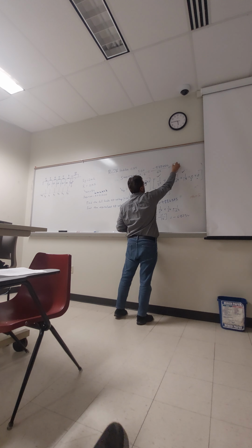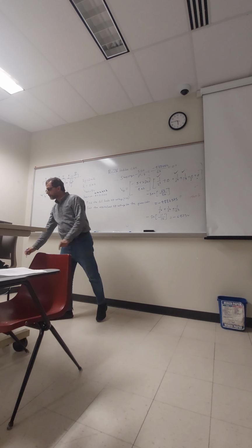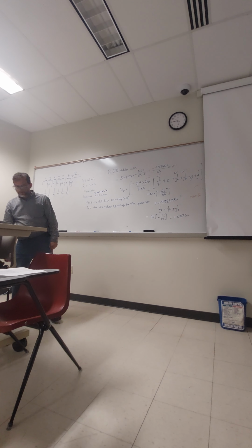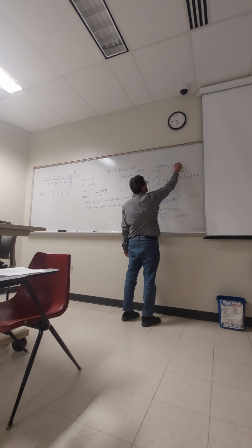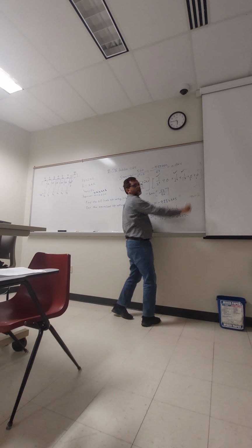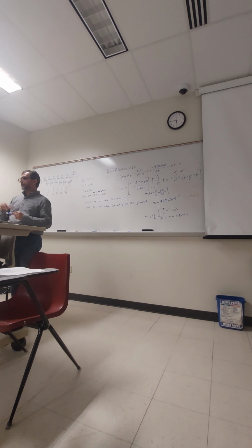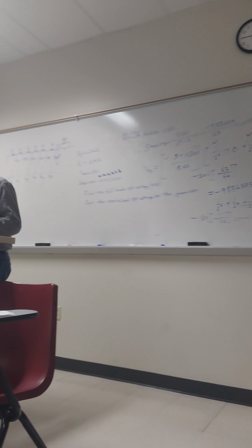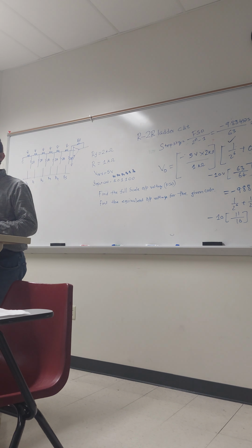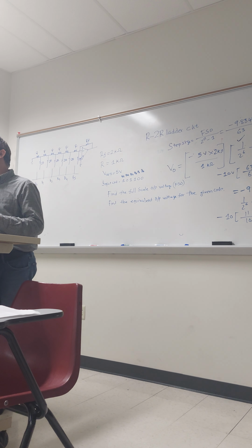It will be 0.156. So this is the step size. The minimum, 1 LSB. For every bit change, the output voltage changes by 0.156 volt.